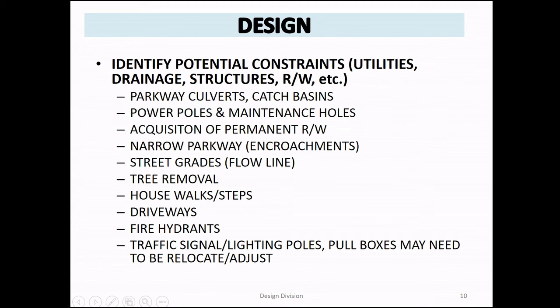And in the old days, and we still do it, I guess, we reconstruct only about a foot or 2 foot strip around the new curbing, around the new gutter. But if we have this issue, instead of doing 2 feet, maybe 4 feet will help. But keep an eye on this. If not, you're going to be trapping water.